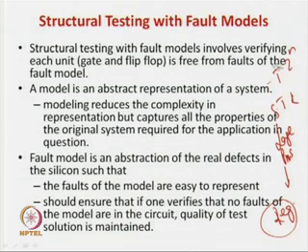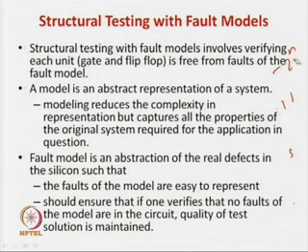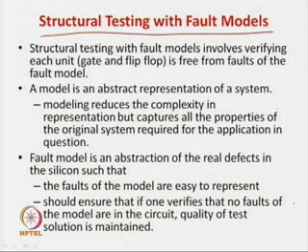So now what we have to solve is how we can handle the large number of registers and also 2:1 multiplexers in structural testing. Again, what came as the solution is structural testing with fault models. Again, what we have seen in the last example is a structural testing with a gate as a unit, or a full adder. Then what do you verify?